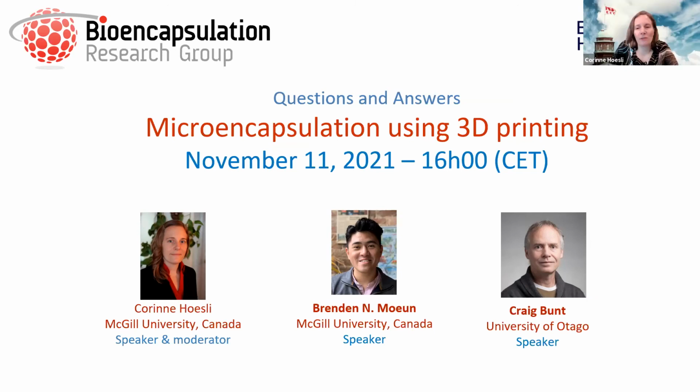And I was wondering also if it changes the actual ballistics, the fact that it's 3D printed, or just upon impact. I know it's not something easy to measure. Yeah, I did some. It's a good day in the lab when you get to cast ballistics gel. They're not very accurate. The downside is all these materials are incredibly light, and so we started investigating adding some dense iron, things like that, zinc oxide, to improve the ballistics. So the major issue at the moment isn't that they're 3D printed, it's just they're too light.